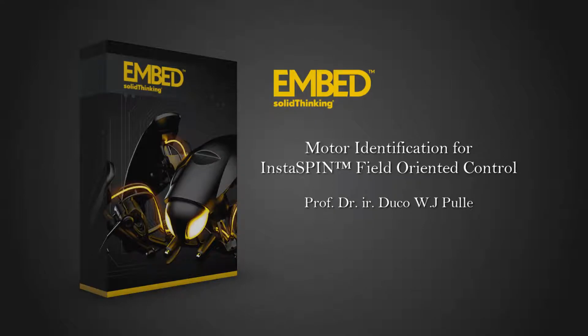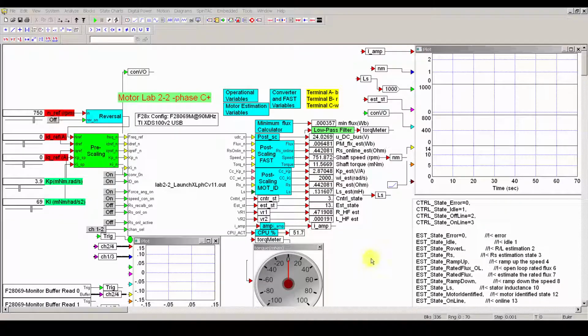application for motor identification. In any encoderless application, you need to identify the parameters. So in the permanent magnet machine, you need to identify the inductance, the resistance, and the flux. And there is a unique routine here, which the algorithm goes through, which will take you through the steps in about 50 seconds. And in InstaSPIN, we show the current, the speed, the inductance, and the various states which appear as we go through this, and we analyze it during the course.